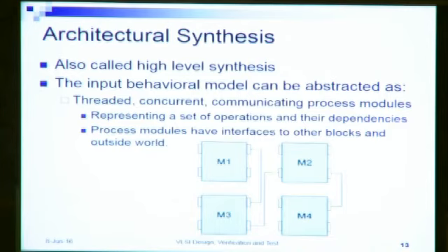Architectural synthesis is also called high-level synthesis. The input to this is a behavioral model which can be abstracted as a set of threaded concurrent communicating process modules. The behavior will be its input, and it will be represented formally as programs.